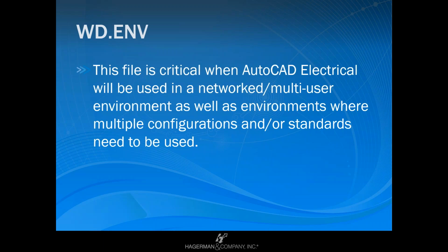But why do you really care about the ENV file? If you are an independent person working on your own laptop, this file is not very critical to you because you can set within AutoCAD Electrical all the different things that we're going to be talking about. However, if you are sharing this within a team, that's a great example. You want everybody to look at the same symbols, the same reports, the same icon menus. You want to be able to share that data because it makes you more productive so that everybody's not doing their own thing or recreating the same drive symbol, so to speak. That allows you to share it. It allows you to share catalogs, different things like that.